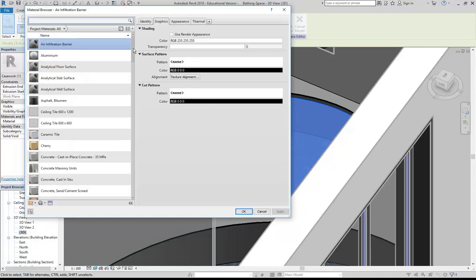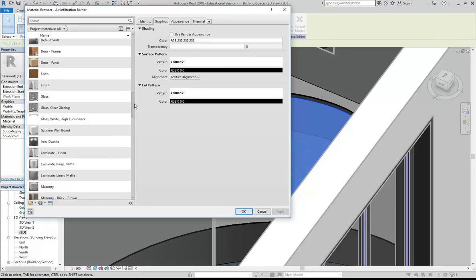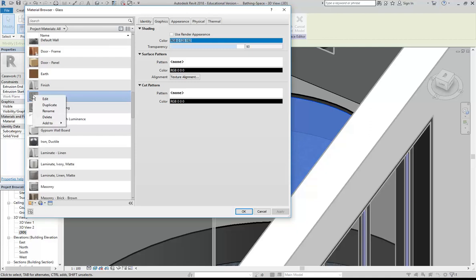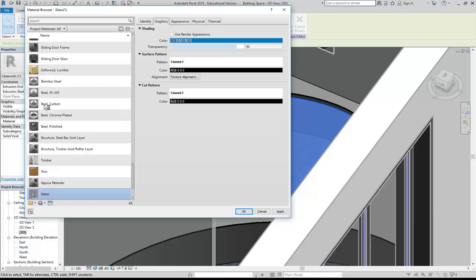And what's in Revit is fantastic. It's got it in the library, but you do have to make it in your file. So I'll just use the same method I've been showing you. Right-click on a material to start, then duplicate, and give it a name. This is for your project. So that's the project's name.